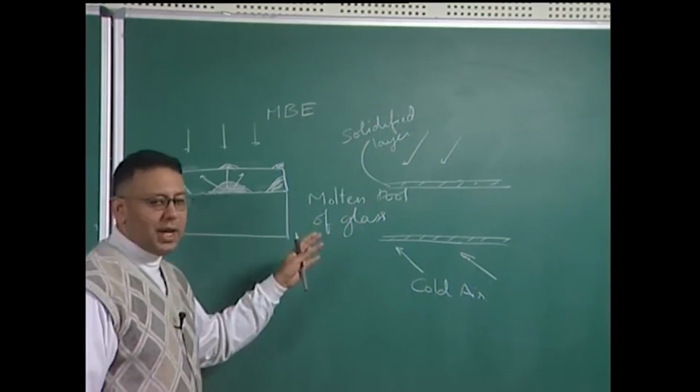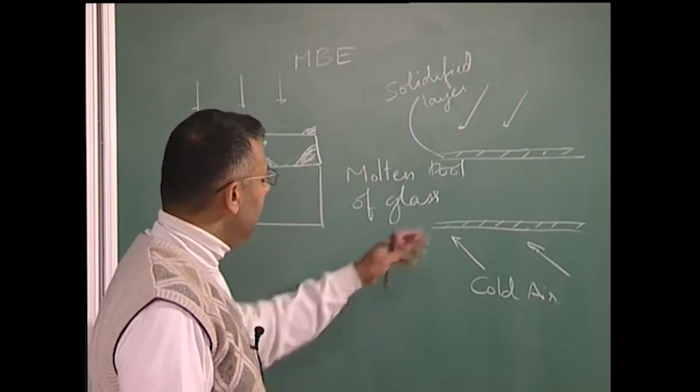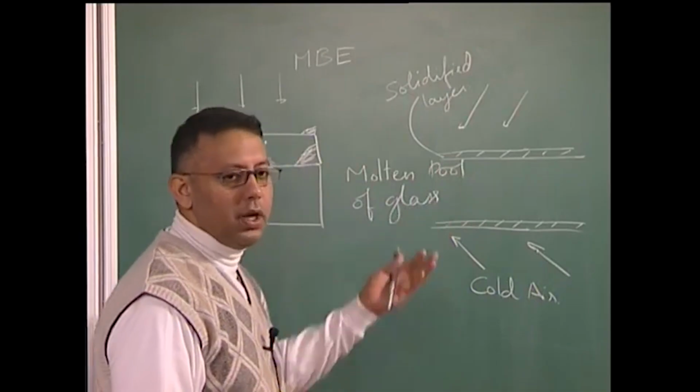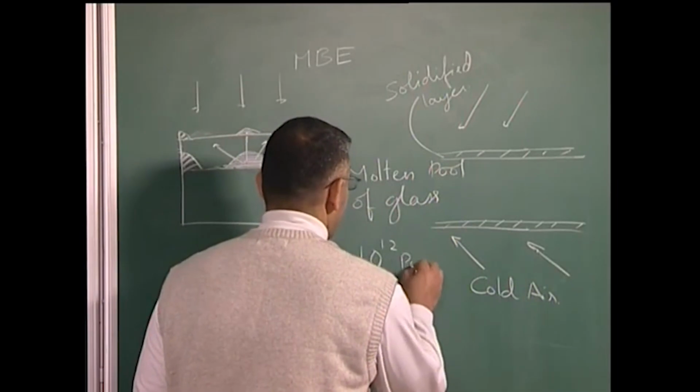Of course, we should note that glass being amorphous, it does not display a strong melting point, but nevertheless its viscosity increases to a certain level, above maybe about 10 power 12 poise, where it can be considered as a solid.